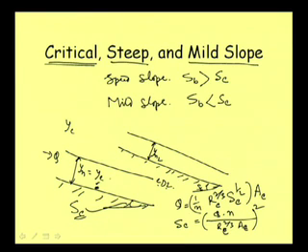Now, coming to this condition, if you refer to this diagram, we are talking about the critical slope S C, and for that we are getting this much depth y n, which is equal to the critical depth. Now, if our slope exceeds this value, then it is steep slope, and when the slope is more than that, depth will definitely come down, like this.